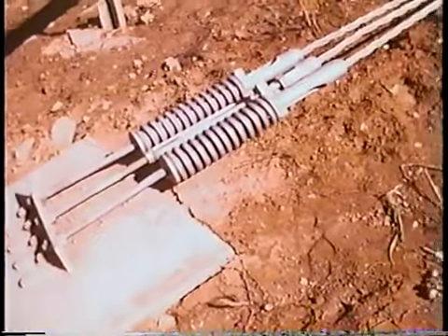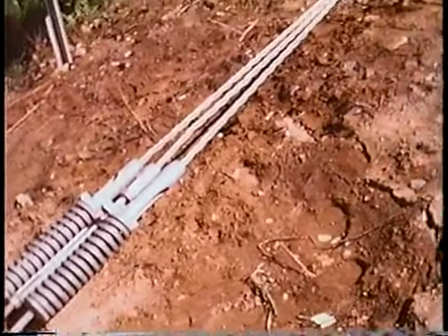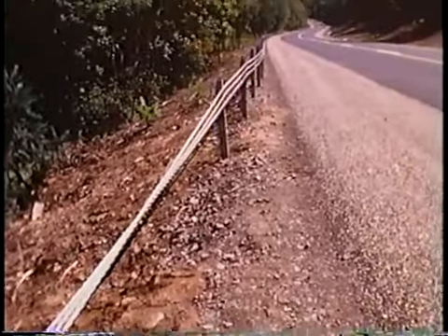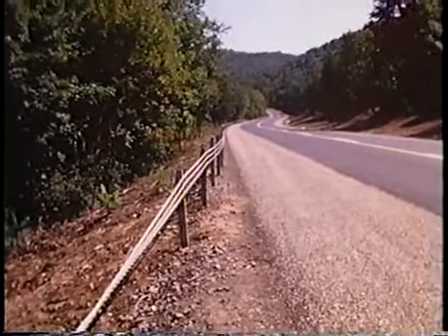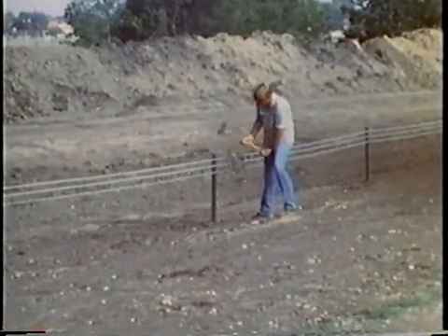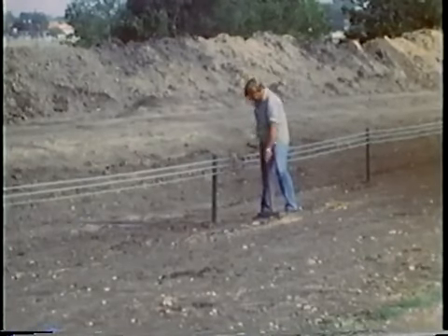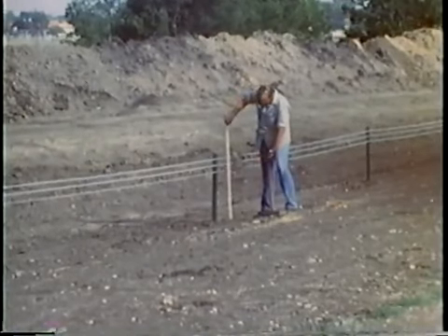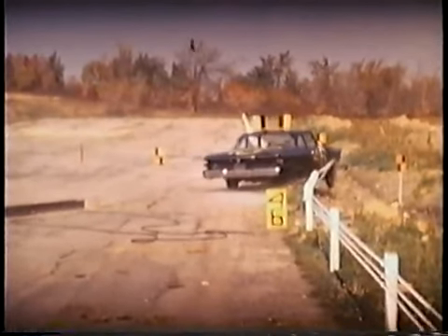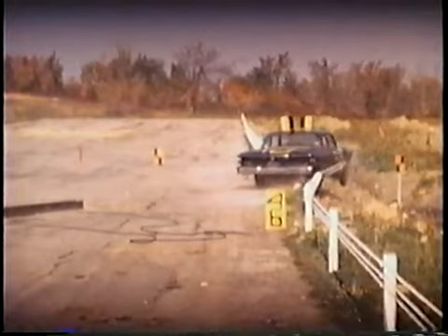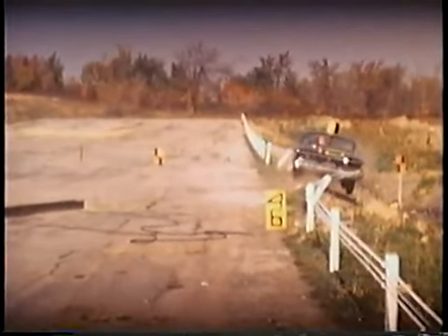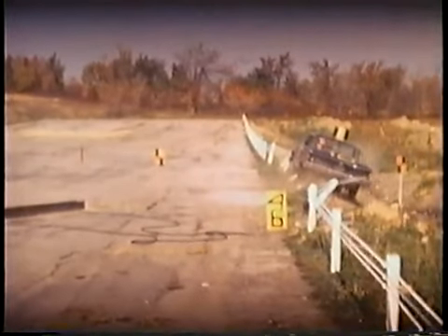This videotape will show the results of recent research efforts to improve the performance and decrease the cost of cable guardrail systems. There are a variety of advantages to using cable systems rather than other types of guardrails. They are easy to install and cost about 1/3 as much as typical strong post W-beam guardrails. The large deflection characteristic of cable guardrails can be advantageous where there is adequate area behind the guardrail. Large deflections cause the impact to be softer and therefore less harmful to occupants.